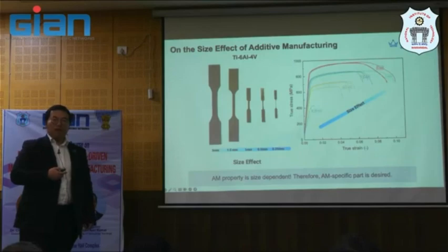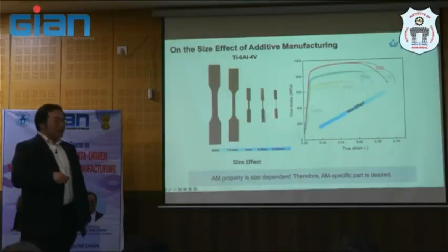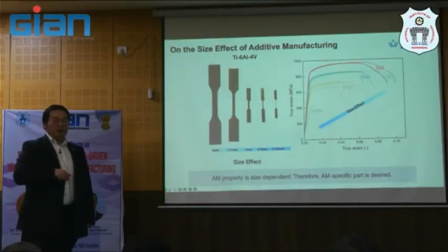That is something we haven't done. I think in this one is titanium 6-4. There is a dedicated paper for this one. I can't remember it. This is not my work anyway, it's my colleague's, so you may look at that. But this is Ti-6Al-4V. That means after post-treatment, even that is columnar grain prior beta. I have to say it's different from nickel-based superalloy structure. So I'm not sure. Probably yes.